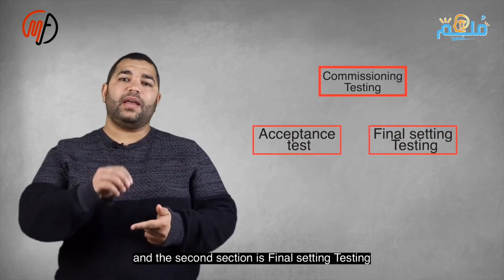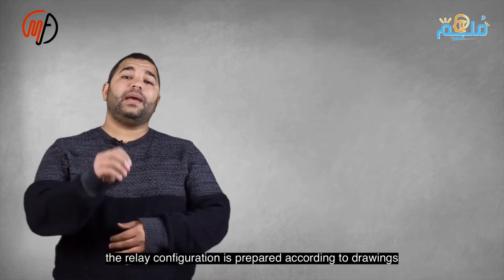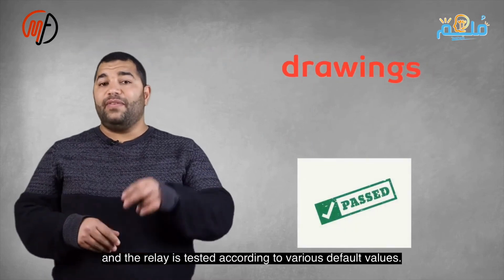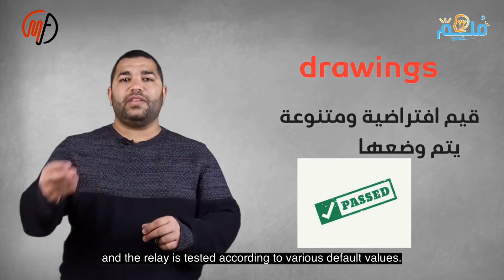During commissioning, we conduct functional tests for digital inputs and outputs, metering tests for current and voltage inputs, and pickup and timing tests for protective functions. Finally, we check the relay logic, ensure the LEDs work, and verify that the relay model number matches the drawing.